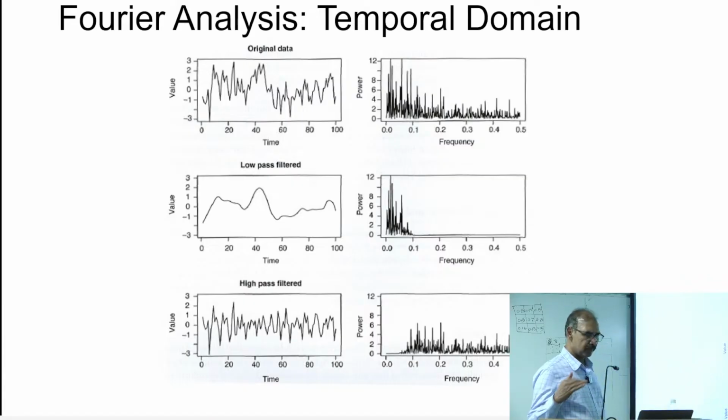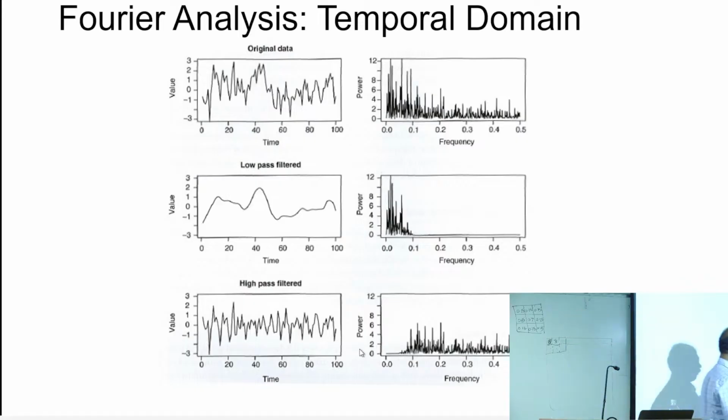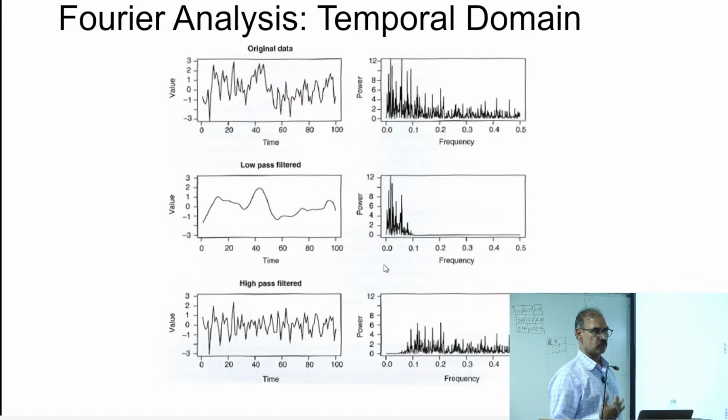And the lower bound is 0.01 because if there is a drift, then setting a threshold at 0.01 is going to exclude that drift. And after 0.1, you have your respiration and heart rate, so the band is used to exclude them.